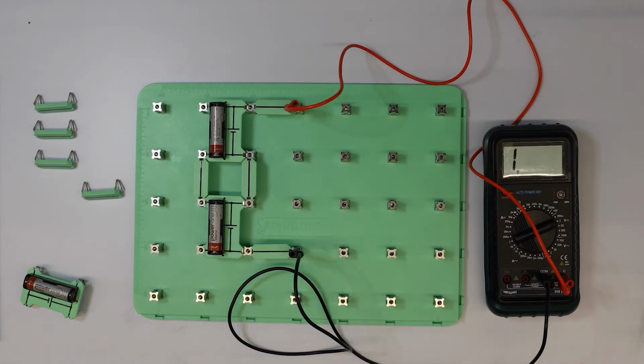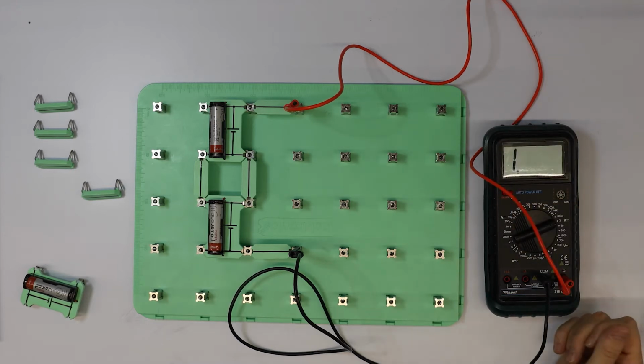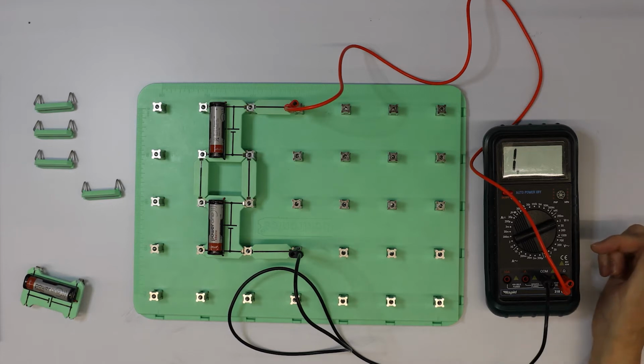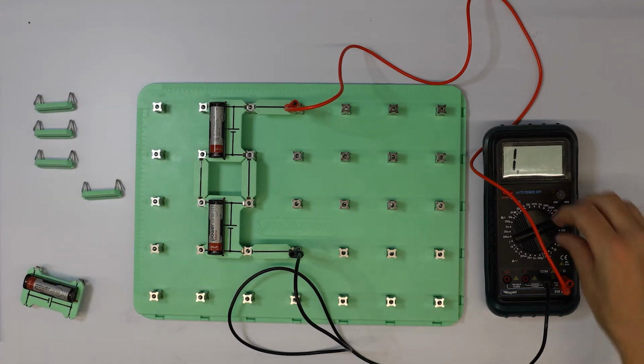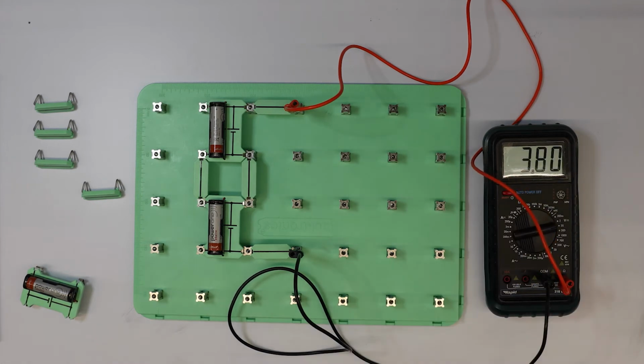So if I put the lead in here, you'll now see that the display on the multimeter is reading 1. And what that's telling me is, because the reading isn't changing, it's not reading 1 volt, it's telling me that I'm now out of range, because my range setting was only set to 2 volts. Now, if the first one was 1.6, every chance this is going to be about 3 volts. And so what I need to do is just increase that range setting. So I'm going to increase that range to 20 volts now.